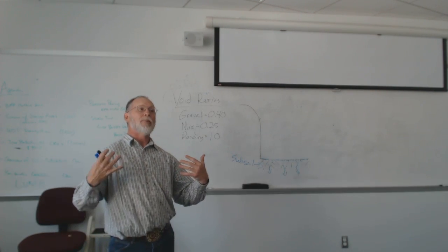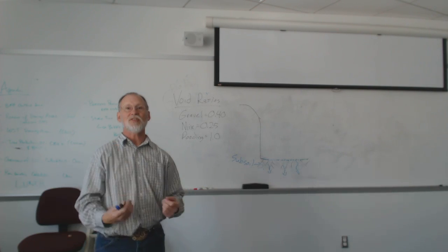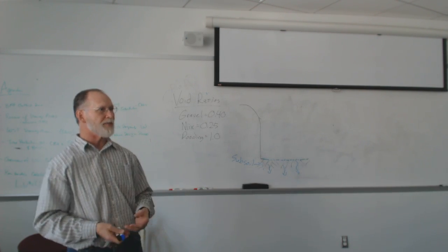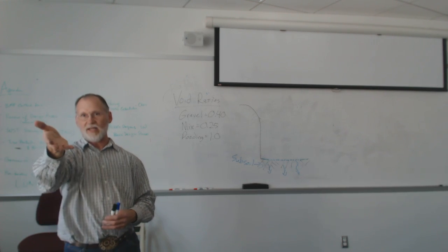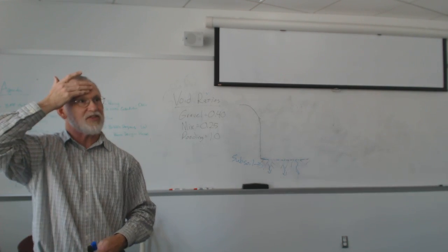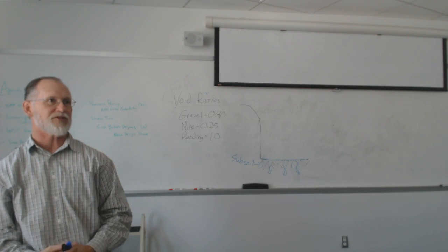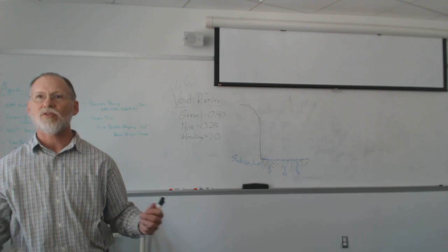But part of my job is to explain, this is how it works. Once you explain politely what's got to happen there, they understand. That kind of goes with that contractor training. Once they understand this is what has to happen, you need a rough surface. If water won't soak down through that surface, it's not going to work. They're like, oh, well, I can do that. So it's a matter of training.